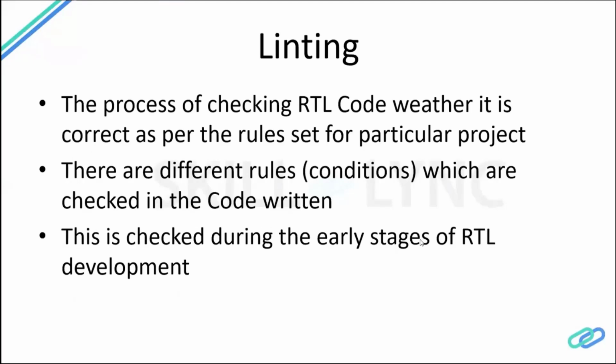I hope you are clear on whatever I have told till now. So now we'll go into a little bit of linting. I'll just explain what linting is, what kind of checks we do, and what tools are there in the industry. What we are checking is whether the RTL code is correct as per the rules set for a particular project.